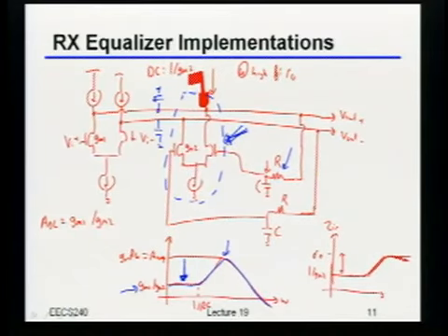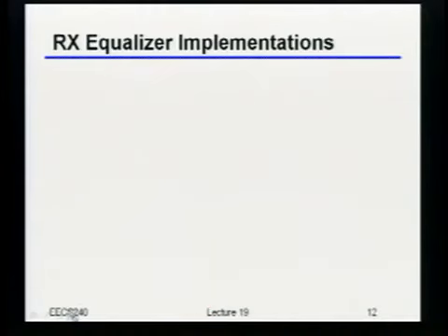So in other words, what I would much rather do is somehow reuse this same amplifier without changing its power at all, but just selectively throw away gain at low frequencies. Okay? Because if I can do that, I can get the same transfer function, the same functionality, but I don't have to spend extra power for it, and I don't have to add extra noise for no good reason. Okay? So just based on that, anybody have a guess as to what else you can do to make it so that you don't change your power at all, or at least in a very minimal way, but just throw away gain at DC?